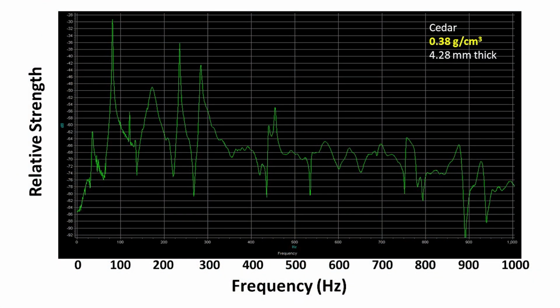Here's the spectrum, and on the x-axis is the frequency in hertz, which means the number of times that the board is vibrating per second. But you can also think of frequency in terms of pitch, so that at low frequency you have low pitch, and at high frequency you have high pitch. On the y-axis, we have the relative strength of those pitches, so that each peak that we see corresponds to the distinct pitches that we hear when we tap the board.